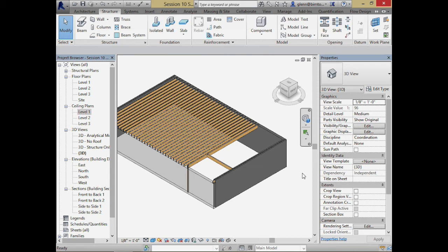That number is, where we did it, 40 times 5, 200 times 1.3, 260, more or less. Okay, excellent. Things are looking good. Now, 20 feet, we'll get a little longer. 30 feet, that much live load. Or if I space them every 24 inches, it's all just how much load you're accumulating.